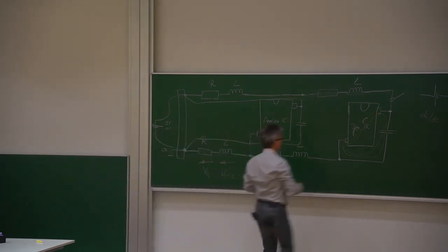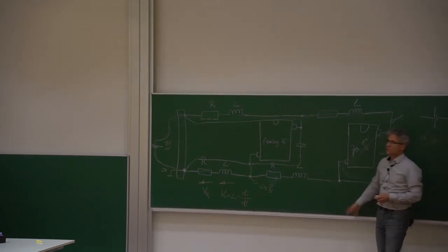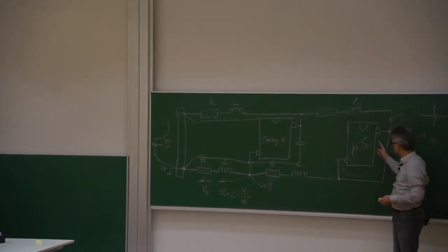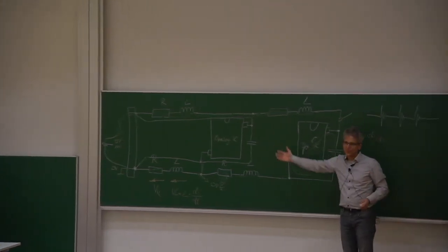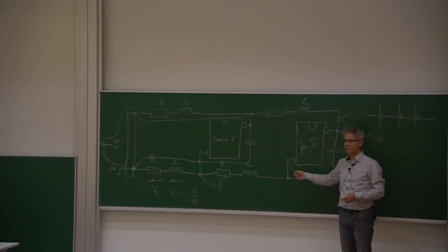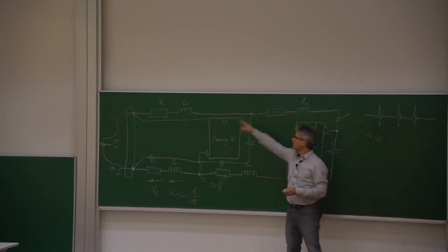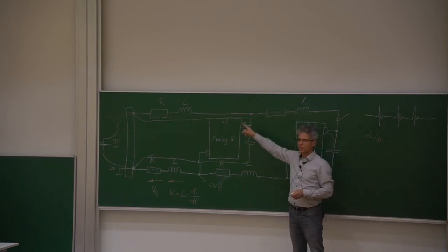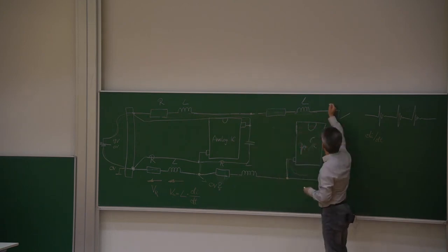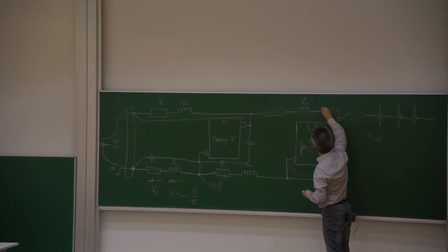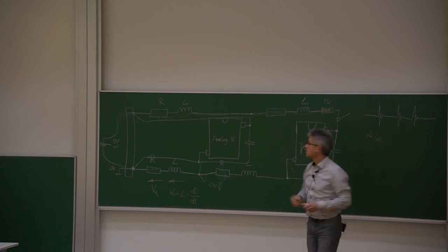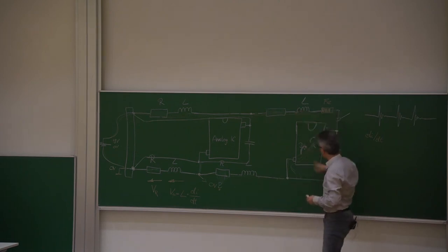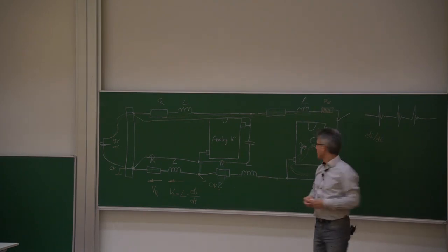Sometimes people are also using additional filtering elements in the power supply because the decoupling capacitor, as I mentioned last time, is not fully effective over the whole frequency range. It's only low impedance in a certain frequency range around the resonance frequency. So still some di/dt current spikes or high frequency content will come out of the big loop. And in order to avoid that, some designers are also designing here a ferrite bead to have a high impedance in this direction so that more current is drawn out of the capacitor. Okay, anything else?